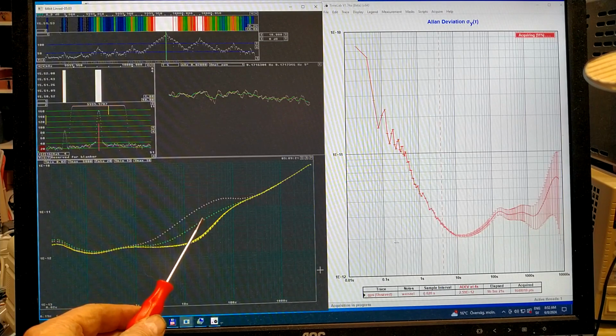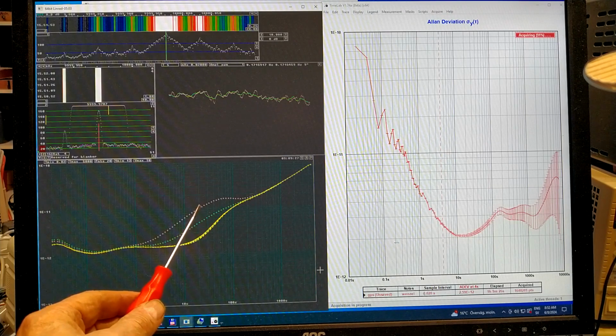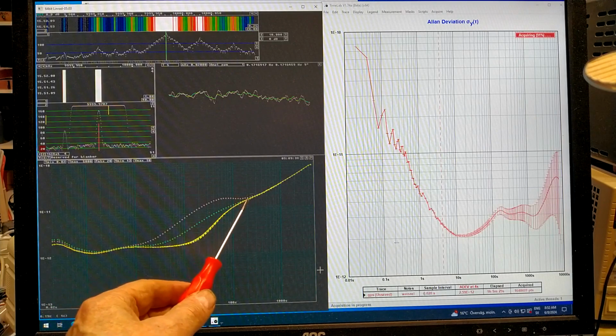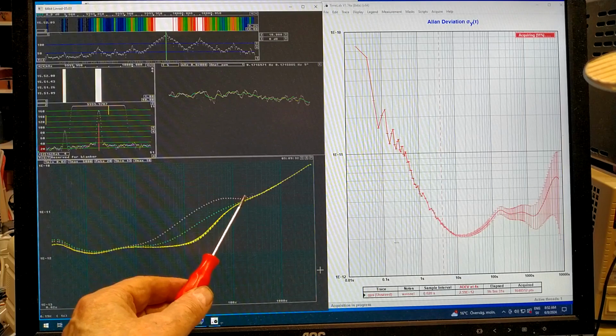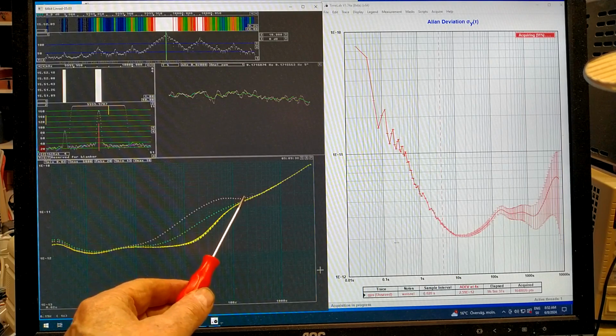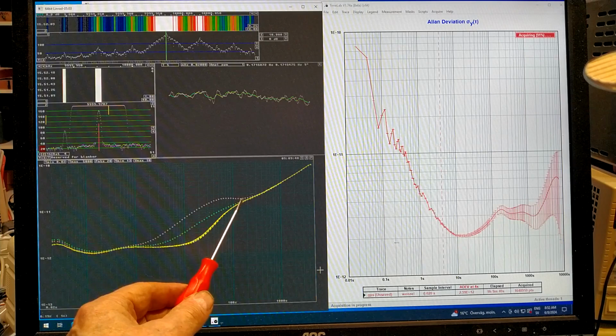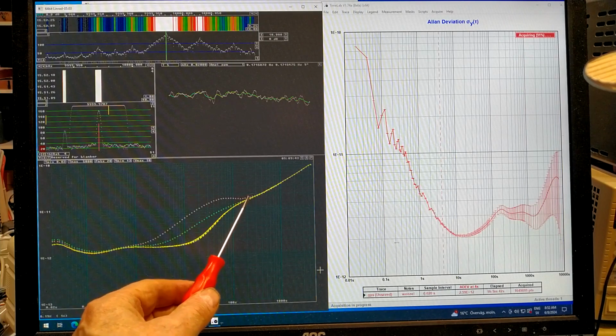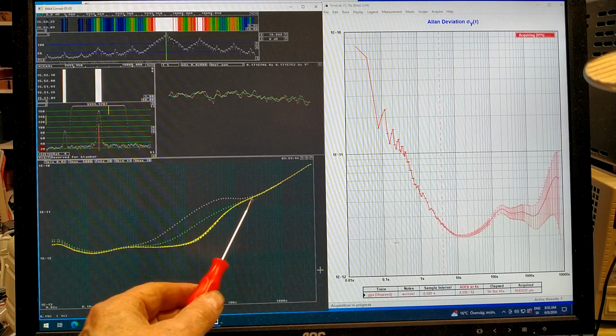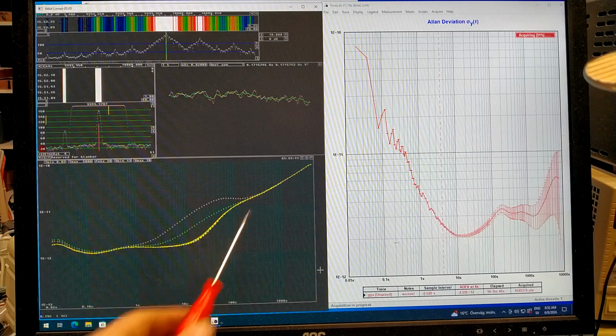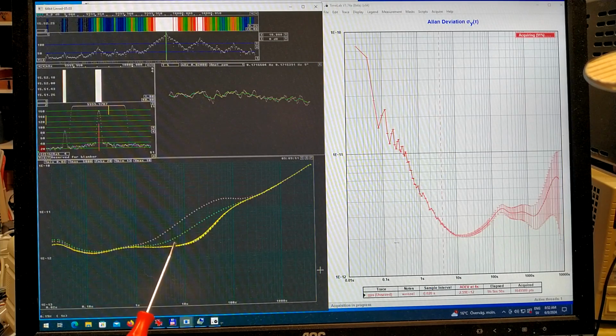because there is the PLL loop and some of the noise on channel 1 is transferred to channel 2. And at 200 seconds they are completely phase locked, so the channel 2, the noisy channel 2, is not more noisy than channel 1 because they are locked. So what we see here is the noise from my channel 1 local oscillator. And here is the result of the measurement, the noise from the GPS oscillator.